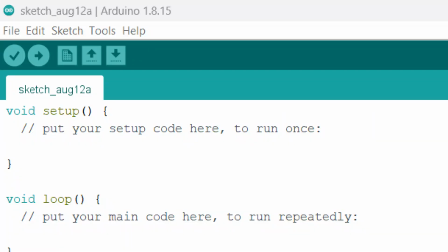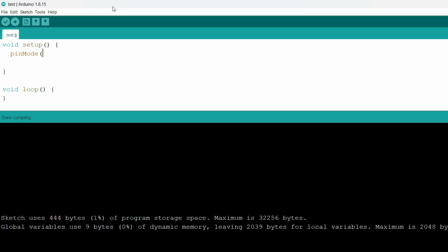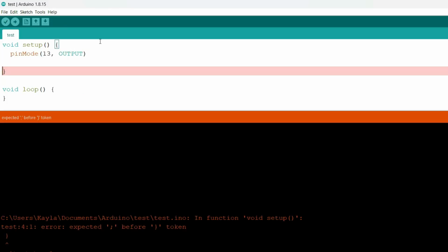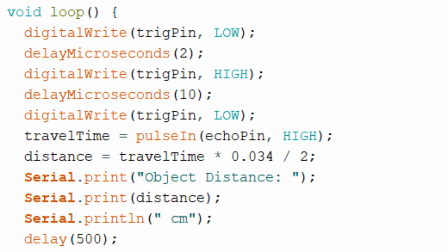The programming language used for Arduino is a variant of the C++ language. In this environment, programs are called sketches. Both capitalization and punctuation are important. A mistake in either of these things will create a compiler error. Certain text like function names or input parameters change colors when entered correctly, which is a helpful feature of the IDE to know if you've missed something.